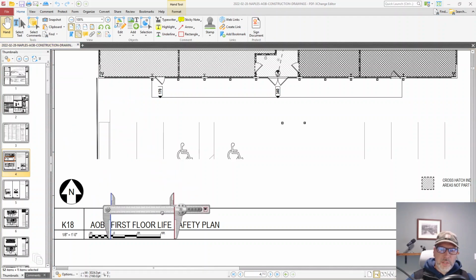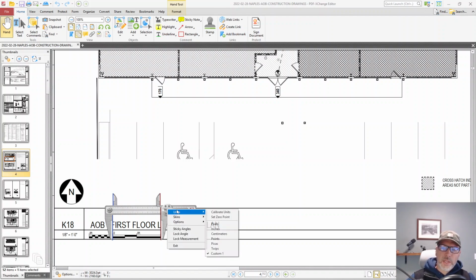So here's how you can do things to verify the measurements. With this item, I will bring it down and I'll line it up on the furthest pieces. And it has little screen keys, so right here I'm using my arrow keys, moving it back and forth. And then I'm going to move the right side over, and I'm going to go with the furthest distance because that'll give the lowest margin for error. If I come up here and hold over the 16.51, because that doesn't mean anything right now, I can look at what the units are, and in this particular case you can see that we've got different types of units that we can use: pixels, inches, centimeters, and I'm going to use this in a very simple form.